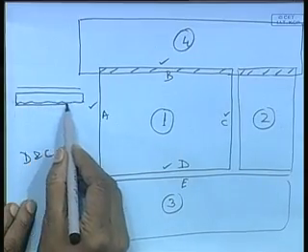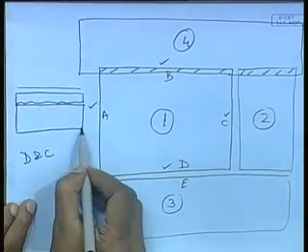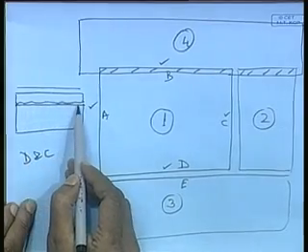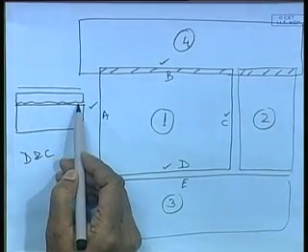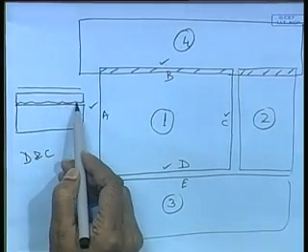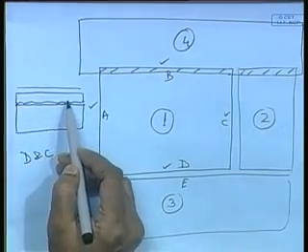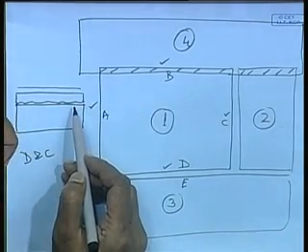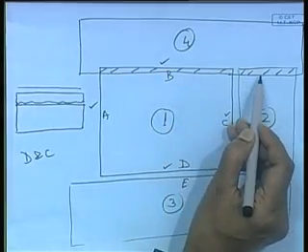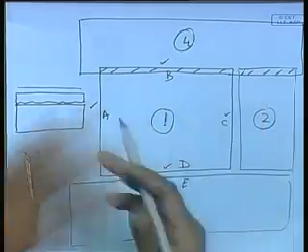Because this is the edge of the plate, to this a finished edge is being welded. So, you see the root gap, because you have cut it manually. Manually means with a gas torch, holding it in hand, and you have to cut, there is no other way. So, that cutting is extra additional work. This welding will again be manual, and since this is not very uniform, you have to continuously manipulate, fill up the gaps properly, and do the welding. So, time taken is more, and weld quality also won't be that good. This extra green material is wastage. So many things are coupled with this.